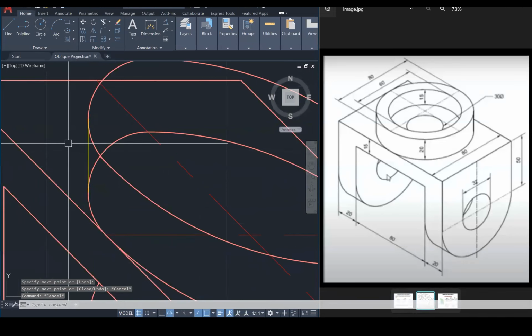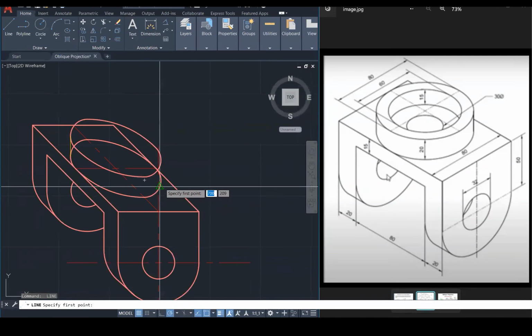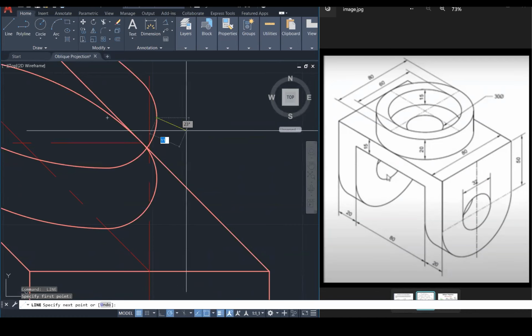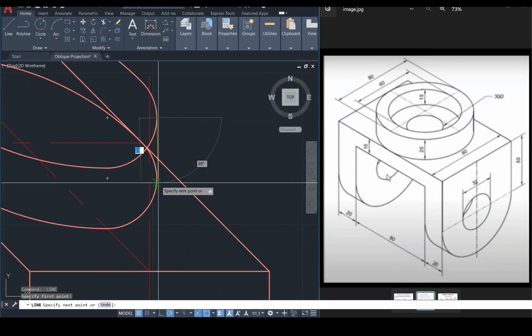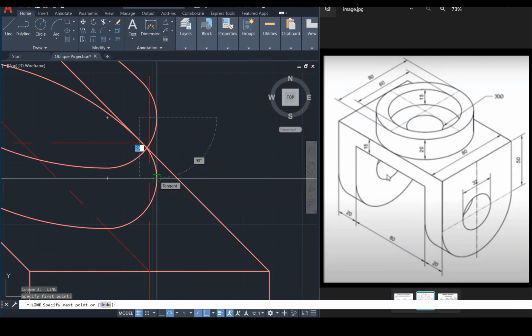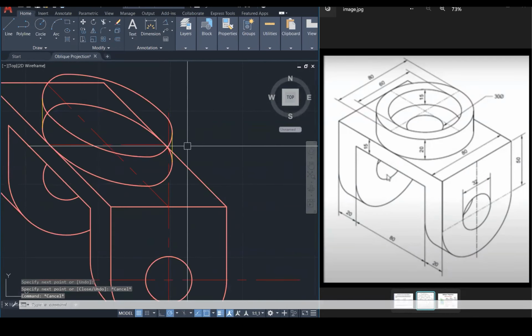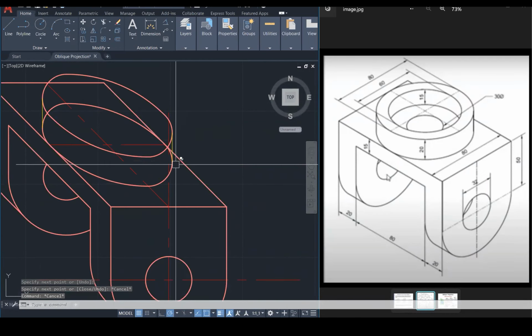Yeah, of placing these tangent lines. So how do I place them? Let's pick a point, which is the quadrant. And then I'm going to come down here until I see tangent, and then from tangent, go back up to tangent. So I start off at the quadrant and I go down looking for my tangent indicator.